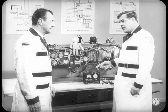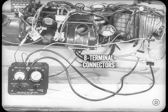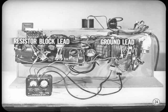I've seen you using the Auto-Temp tester, Bob, but I haven't been able to figure out what it does for us. That's a mighty valuable diagnosis tool, Jack. If you know how to use it, you'll save yourself a lot of time. Right, Tech. Using the tester, you can check out the entire control system as well as the individual sensors and the temperature selector. To hook up the tester, remove the right-hand kick panel and disconnect the 8-terminal electrical connector. The tester has a male and a female 8-terminal connector to match the 2 halves of the servo unit connector. The tester has 2 other electrical connections. The black lead goes to the blower motor resistor block.